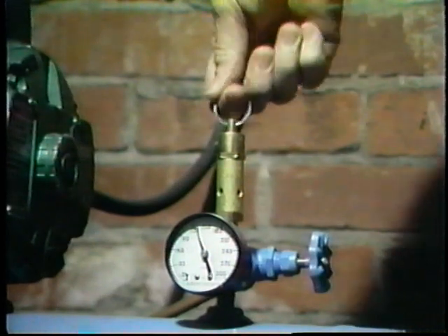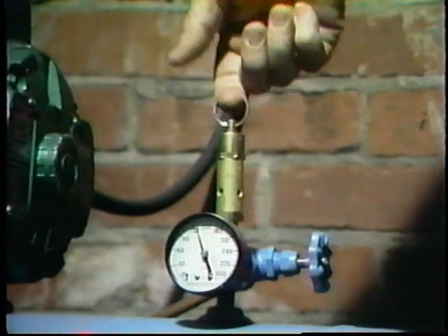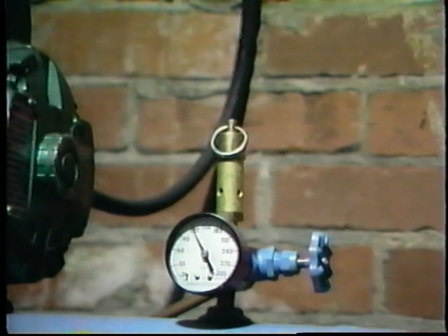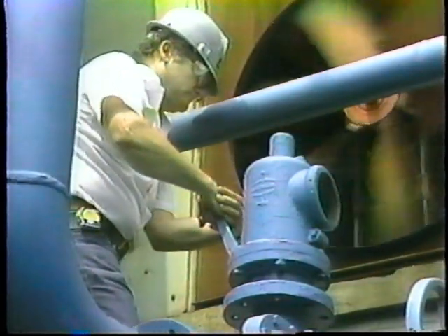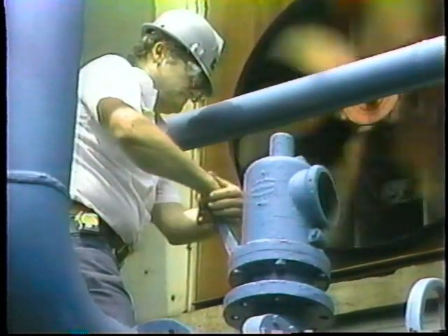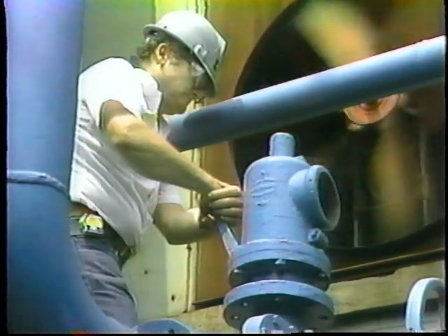Periodic checks of safety relief valves to make sure they move freely is an essential part of a good maintenance program. So be sure to follow the schedule specified by your supervisor and/or preventative maintenance schedules.